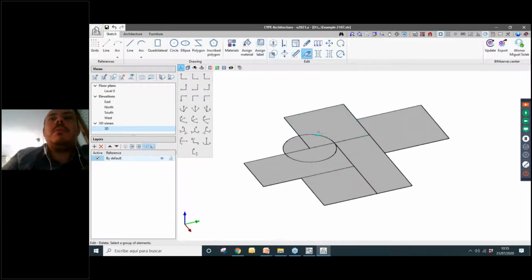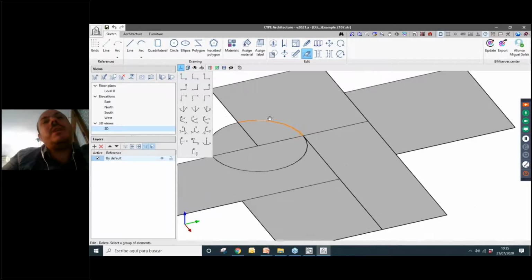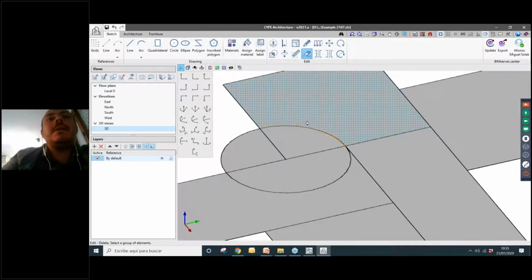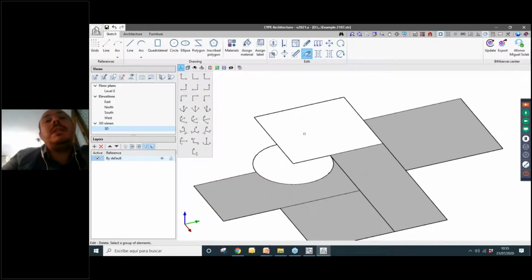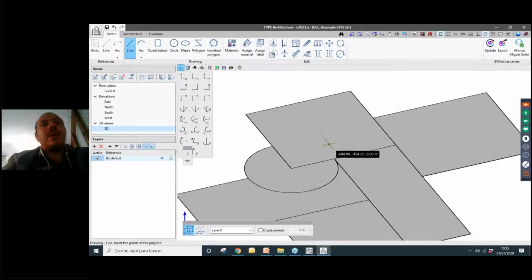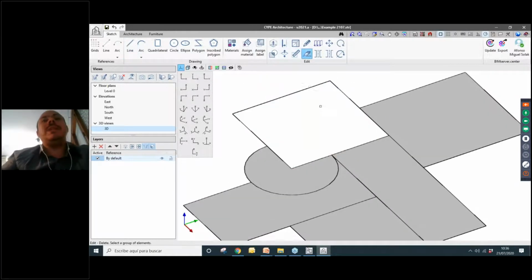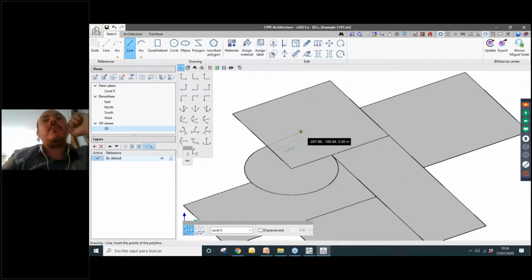Maybe this information here, you can see the little lines that are used to generate a circular arc or circle or ellipse. So these are the little segments that I was talking about before. I would delete that. For example, I could delete these guys here, and when we delete one of the sides of a surface, we can just redraw one of them, and the surface will be generated again. So if at any moment we delete one surface, we just have to redraw one of these sides, and we have the surface again.